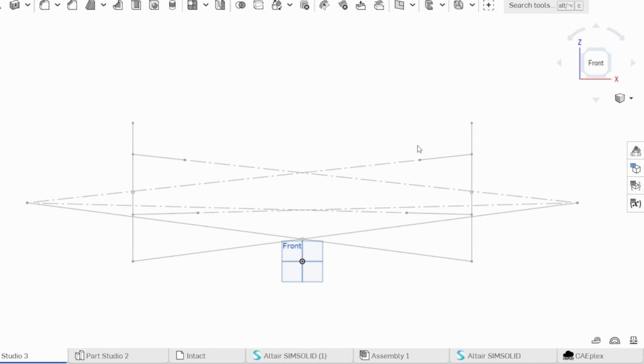Since both A-arms, as I have them drawn at least, are at an angle, both are going to create a vertical component or jacking force. If, let's say, the lower A-arm was straight horizontal, then there will be no vertical component from that A-arm. And the vertical component, since it is going into the chassis, is partly suspended vertically by the A-arms, and the rest of it is supported by the springs and dampers.